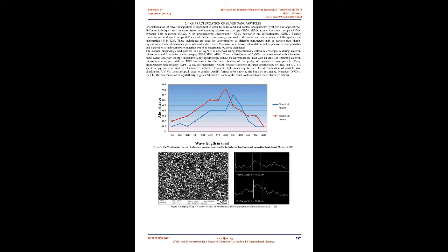Recently, Lu et al. 55 reported on growth of metal nanoparticles, for example, Au and Ag, using DC sputtering systems. The metal targets were sputtered onto ionic liquids to form self-assembly of metal nanoparticles on carbon supports in the liquid. Thus, DC magnetron sputtering could be a potential technique for synthesizing metal nanoparticles. The technique also reduces the complexity of synthesis processes and facilitates control over size, shape, and aggregation of the nanoparticles. 56. However, little research to date has focused on using this technique to synthesize Ag nanoparticles.